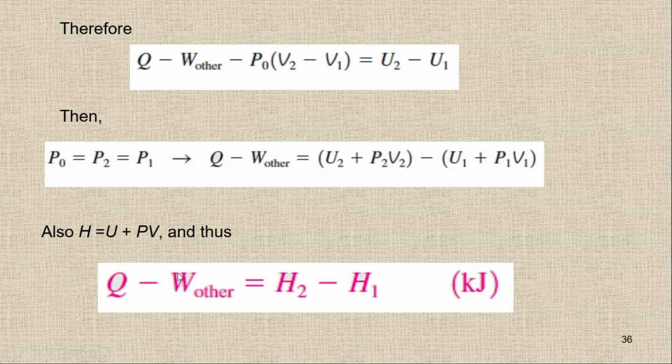Because I was using the first law relationship, I didn't put a negative sign for Q, even though the heat is going out. But when you solve the numerical, you have to put a negative sign. And if I use the energy equation, then you have to put a negative sign with this Q.